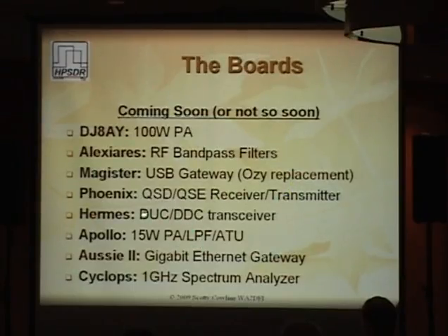It's going to take the Pennywhistle 15 or 20 watt, depending on who you ask and what day it is. Scaled down low-pass filters, so not 100-watt versions, but only 20-watt versions, and an automatic antenna tuning unit, all on the other board, and it's the same size as the Hermes board. So here you go, a 2-board set. They're meant to slide into a Eurocard type extruded enclosure, and you have a complete radio.